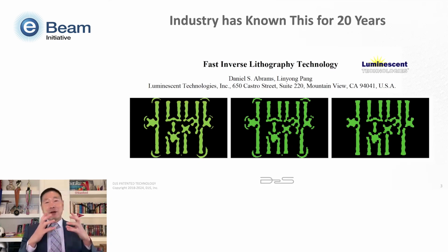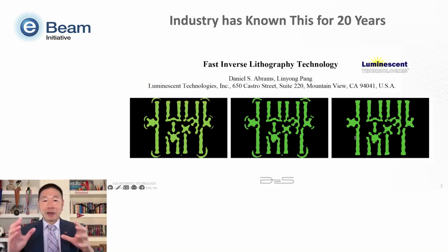That's why the first time I looked at this, I thought, oh, there's no way the photomask industry can accept it. Therefore, we had to Manhattanize those patterns so that the VSB mask writer could write them. That's why we also showed those Manhattanized ILT patterns.